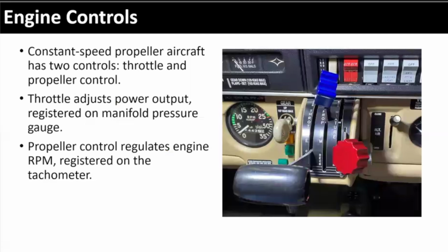So it's the actual prop itself where the blade is turning, right? The pitch of that blade is turning. So this is not connected like it is here. Okay, and it's hydraulics and governors that are controlling that pitch, depending how you set that prop control. There's going to be a picture in here.